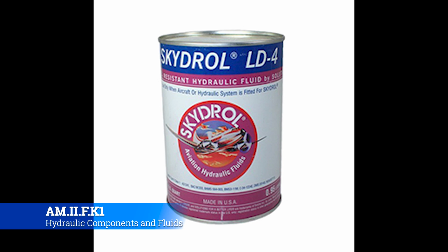And so as you start to progress up in the complexity of aircraft, you get more and more hydraulics, and it doesn't take very long to outgrow 5606 and 832, and you start getting into all the ester-based fluids like Skydrol. There are other brands out there. Skydrol is just a brand, but it's probably the most prolific and most common brand. Another one that you may run into is Hyjet. I've never actually seen it used. I think I've always serviced with Skydrol.